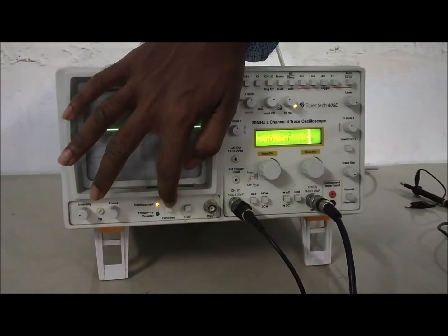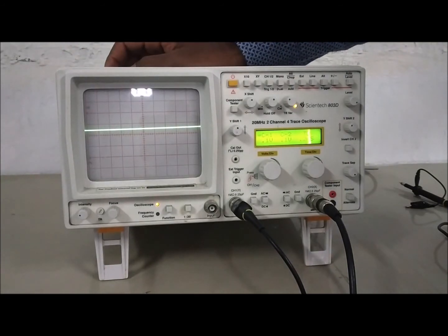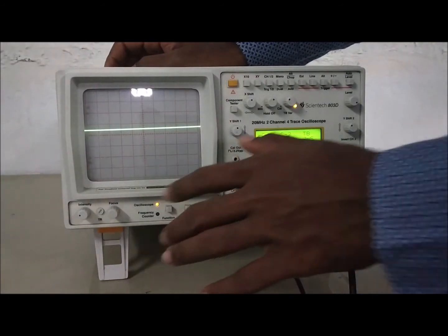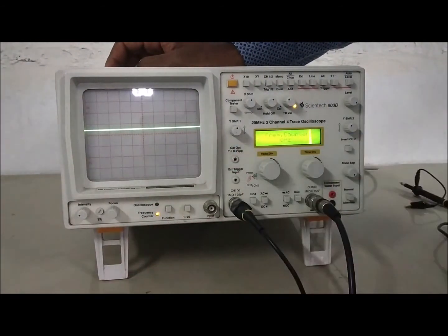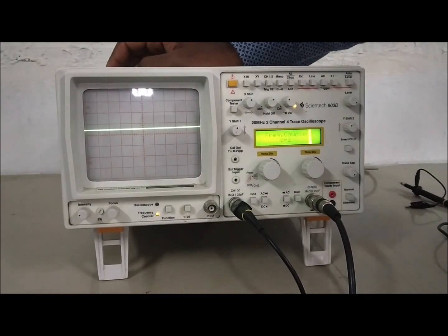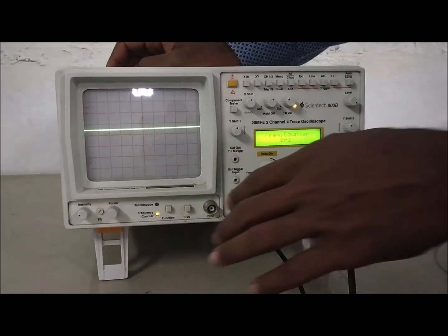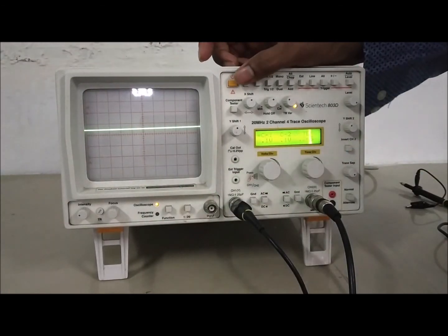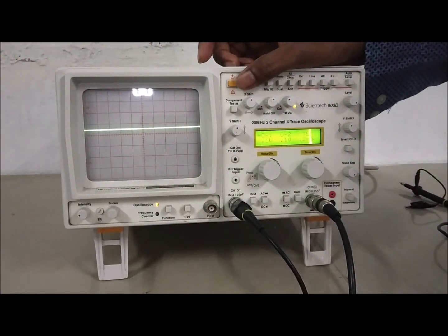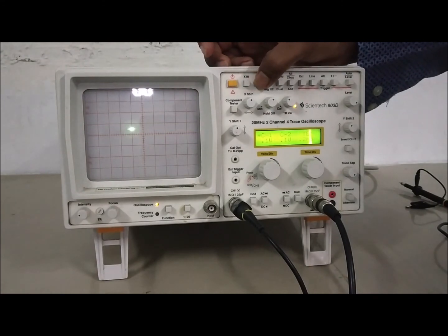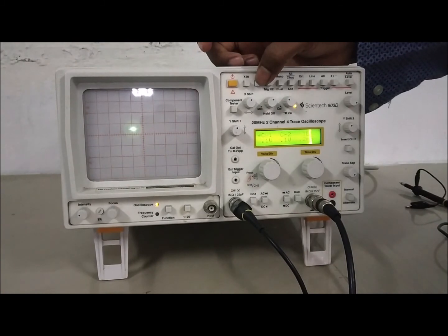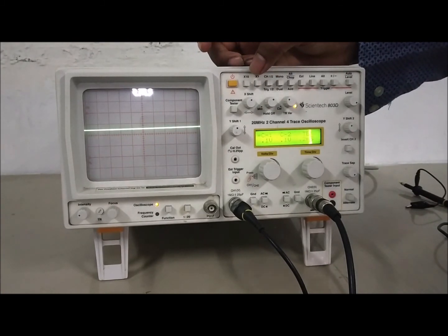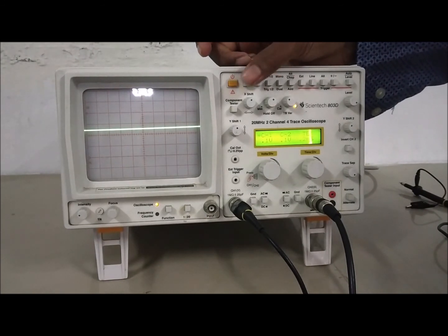There is a button called function. If you do not press the button, then this will be in the oscilloscope mode. If you press the button, then it is in the frequency counter mode. It only measures the frequency of the signal. X10 means you can observe the signal 10 times the original signal. XY means this will simply give a dot for the line. This is how there are different knobs. We have learned the most useful knobs for us now: channel 1, channel 2, mono, dual, X shift and Y shift.